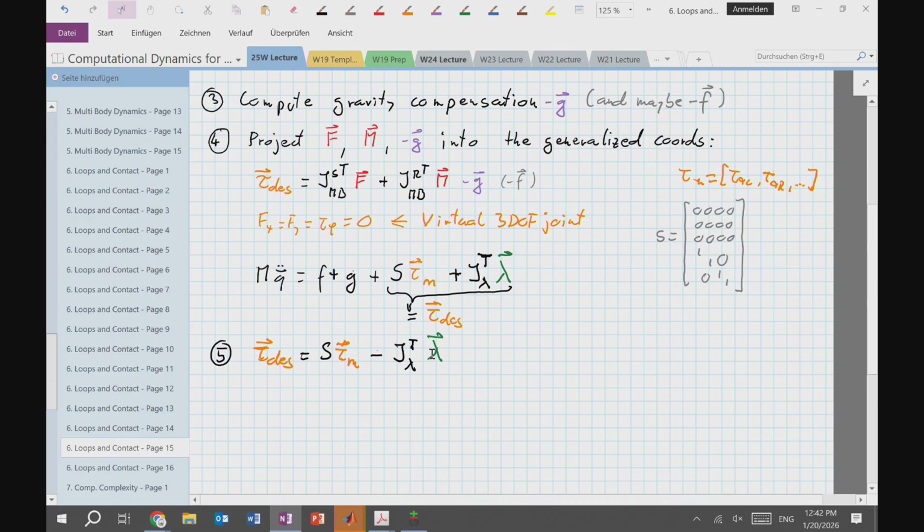So one foot on the ground. Things look a little bit better. But essentially what you generate is one foot on the ground and then some robot on top of it. You generated an inverted pendulum. And no matter what you do, this degree of freedom is doomed, right? That's unstable, you're going to fall. And this is what we see here, because then I have 4 here, 2 here, gives me 6 total, still 1 missing, right? So there is 1 degree of freedom that I cannot control. So in a sense, I cannot keep the system upright.